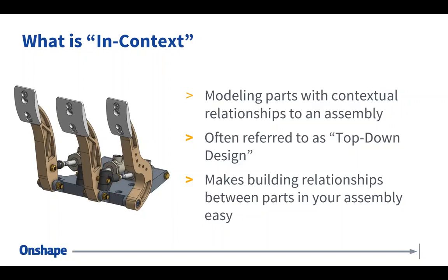Now, what is in-context? If you're not familiar with the term, it just means you're building parts, you're modeling parts with contextual relationships to an assembly. So if you think of a traditional new user who's just getting started in a CAD system, they're going to build what's called bottom up. And that means building each part in isolation, one part at a time in their own separate tabs, so to speak, in an Onshape document.